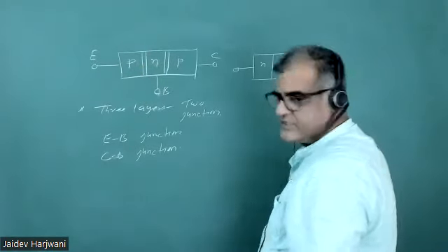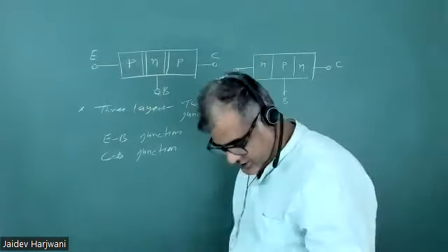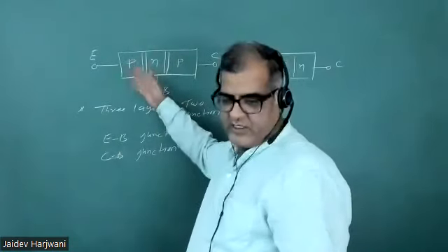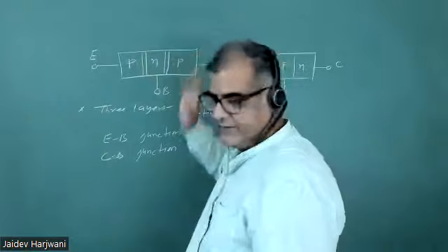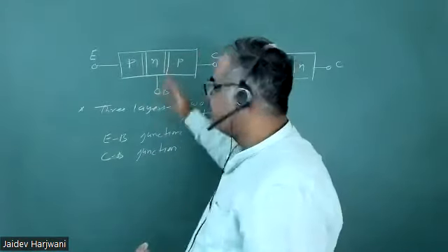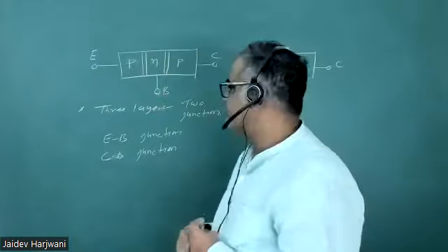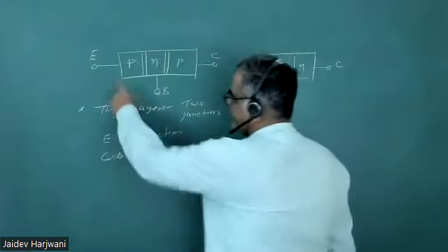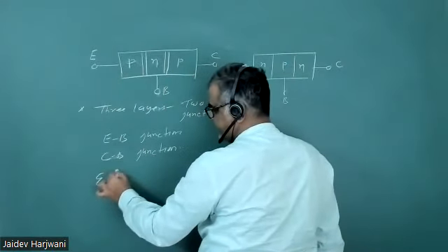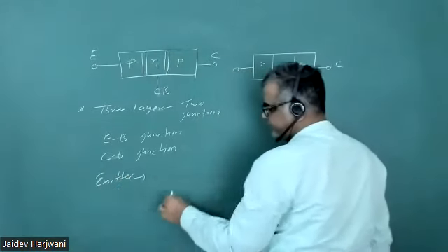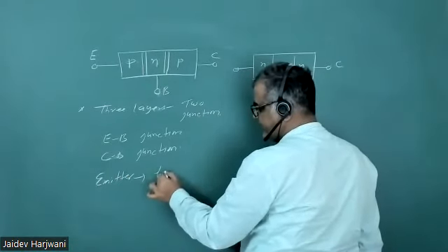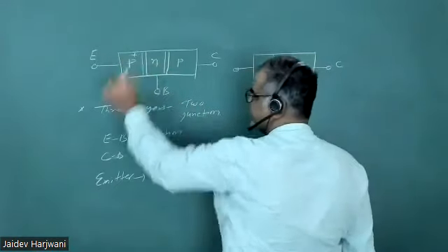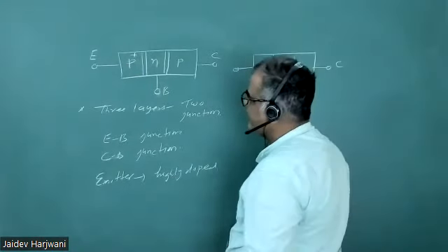Now, what are the characteristics of these layers? These layers are not uniform. They are not similar; of course there's a P type, N type, P type, but other than this, their size is also different, plus there's a doping difference. If you take your emitter, the emitter section is highly doped. If you want, you can write P plus here also. High doping means it is heavily doped.